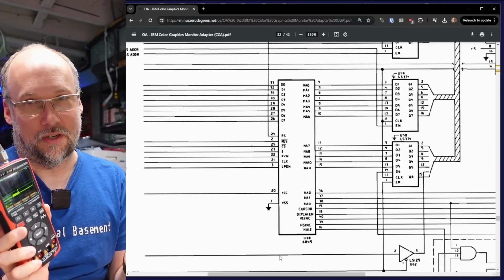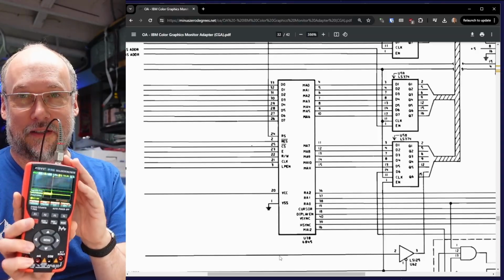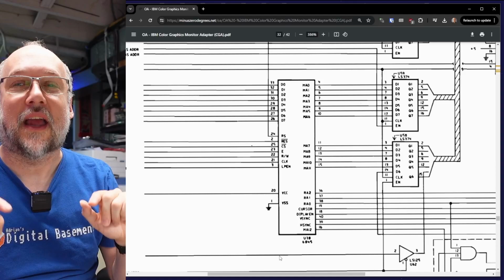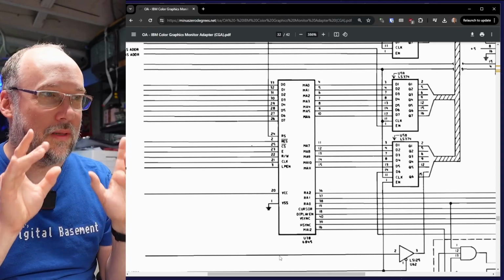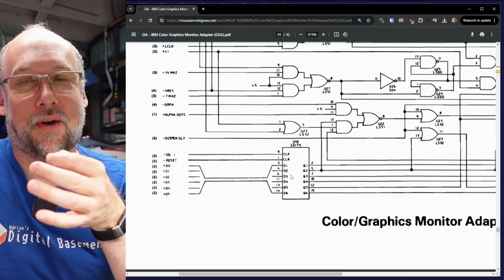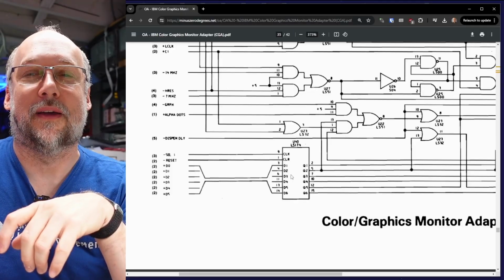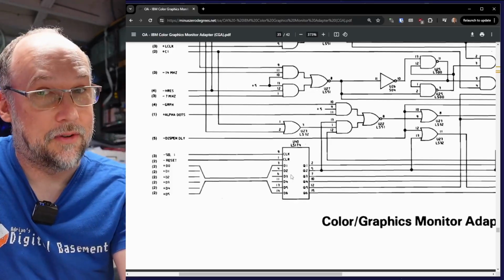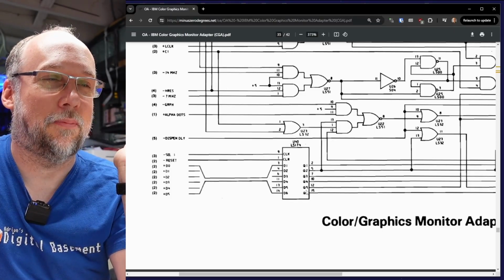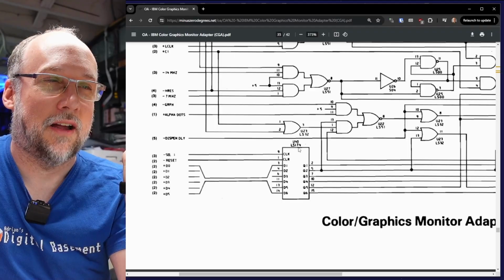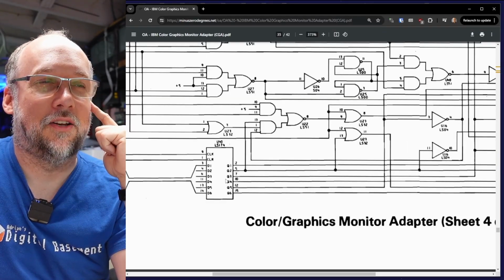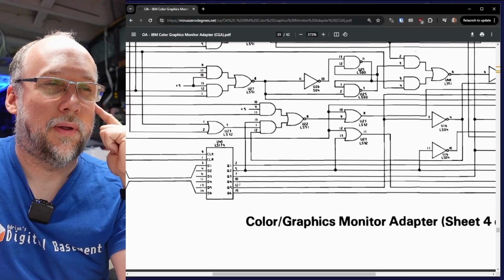And one thing that I should have done, and I didn't do before, is I hooked up the oscilloscope to the output of that signal, and I could see that it was toggling every single scan line, and it had nothing to do with the flashing during scrolling. So I started to look around to see what is generating that bit 3, which turns off the image. I was assuming it was coming from the CRTC, but I was completely wrong. It's actually coming from this chip here, U40, which is an LS174. And it turns out that this is the signal right here, Q4, pin 10.